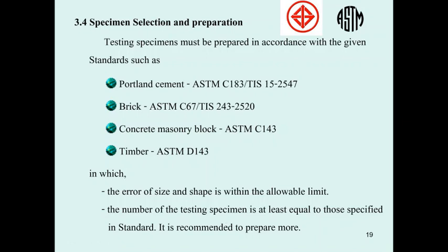Like most concrete cylinders, actually we test only 3, but when we collect the specimens, we collect 5. Why? Because if one of the concrete cylinders doesn't pass the test, we can take the rest of them to represent the concrete we are checking.